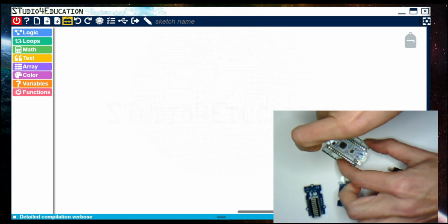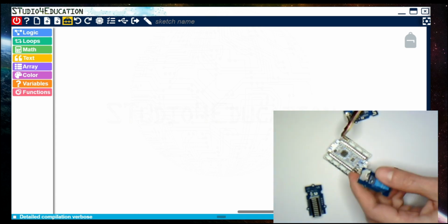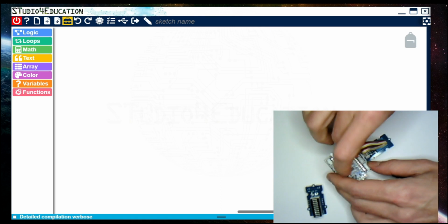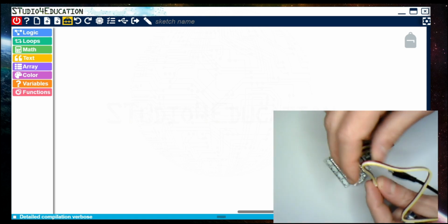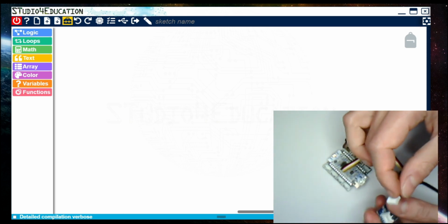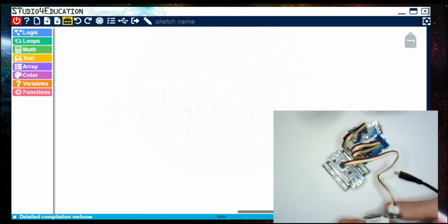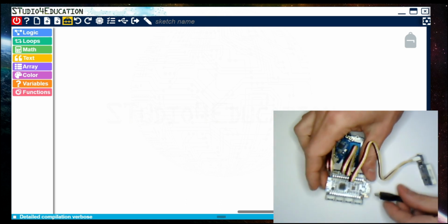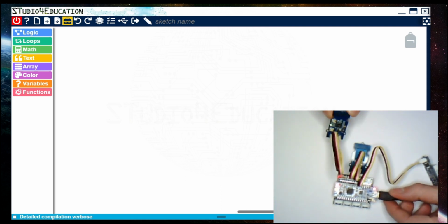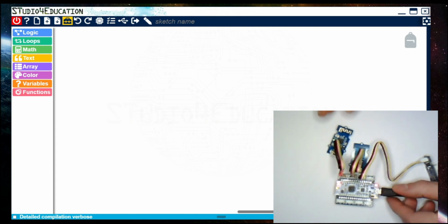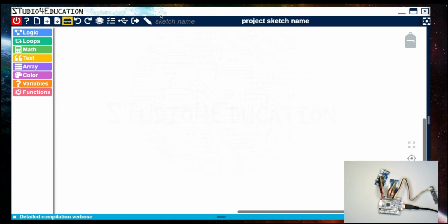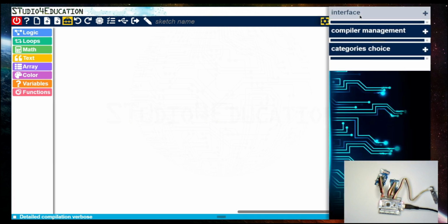So I already prepared this, and so I need to put the Wi-Fi on the port digital pin 6 and 7, and then the temperature sensor on the 5, and the last bar graph on the next port. This is because I already prepared everything, and so I will load the file with the right pins. So this is okay. So the USB cable shows that it seems to work. So we will verify through my program.